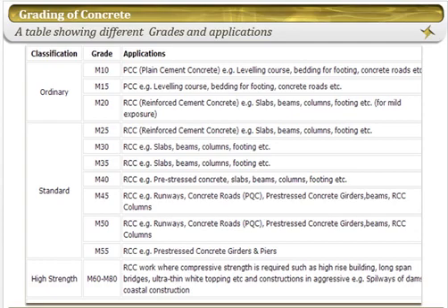After that we go to higher grades, M35. This is also used where the loads are heavier than ordinary loads, and we use M40 concrete and pre-stressed concrete. Because of pre-stressed concrete, we require high bond strength and high tensile strength, because losses are also there. That's why we use minimum M40 concrete grade for pre-stressing work for slab, beam and column also.